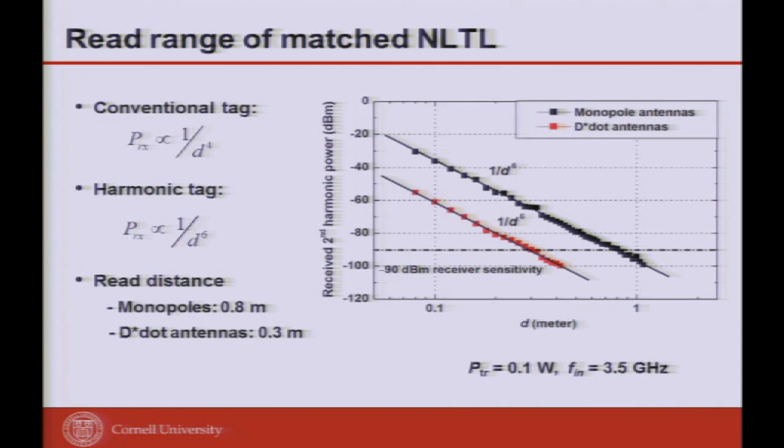Because of the 1/d squared, the amplitude at the receiver side determines how much harmonic you can generate. So the additional downlink d squared is squared, and it becomes d6. You can see the experiments are right on the 1/d6 line. That's free space. Indoors, you get at least another 1 or 2 in the exponent, because indoors is usually 1/r cubed for the overall amplitude.